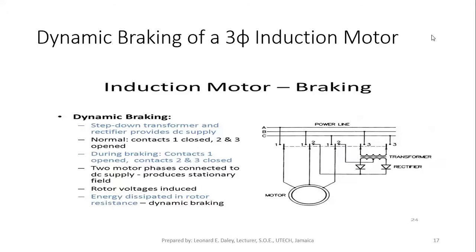All right, so we have discussed so far plug-in and dynamic braking in a DC shunt motor and dynamic braking in an induction motor. I think we mentioned also that plug-in can also take place in the induction motor by reversing the connections to any two of the stator windings.